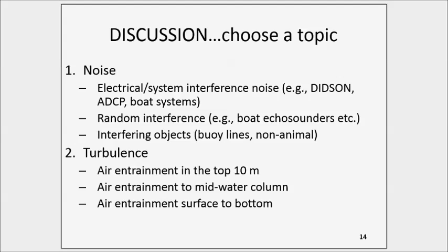The way that we've set it up is we have a central controller on the whole platform, and that basically schedules all of the different frequencies from pinging. So every ping is placed in time with a sufficient amount of decay time afterwards to allow the echoes to decay back to background noise. So we have a 38, 120, and 200 kilohertz EK60, but we synchronize that with a 260 kilohertz multibeam. So it's just another way of going at it.